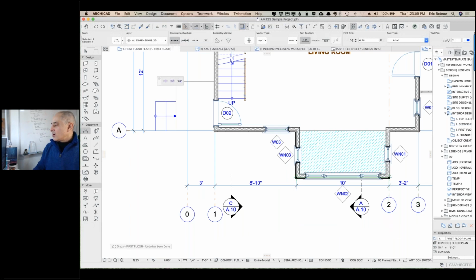All right, so Emil says, is there a way to edit dimensions by using grips? Can do it in AutoCAD so easily, cannot do it in ARCHICAD, and he's mentioned 17. So edit dimensions by using grips. Well, grips, the equivalent in ARCHICAD would be handles. You select a dimension as a whole by going to the edge of it with the arrow tool or the shift key. Now, we do have some hotspots here.